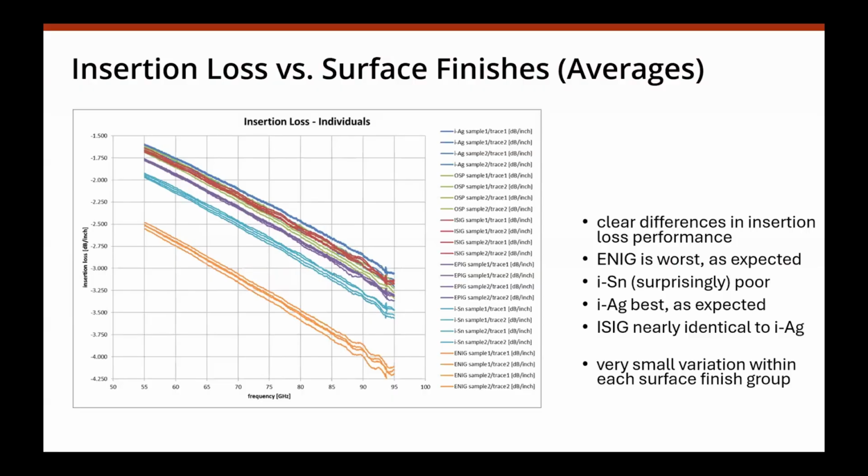So that's, as always, a good area: talk to your PCB fab, ask them about what they have to offer, and listen to their recommendation. Those guys do that day in, day out, so they will have a good understanding of whether a surface finish can withstand the requirements you have from an environmental, from a mechanical point of view, and then combine that with your electrical needs, and then you will end up with a solid design.